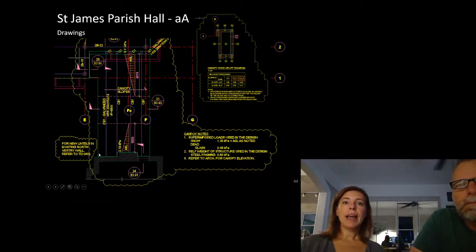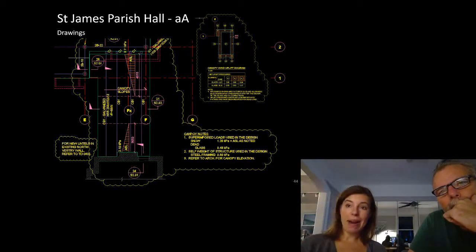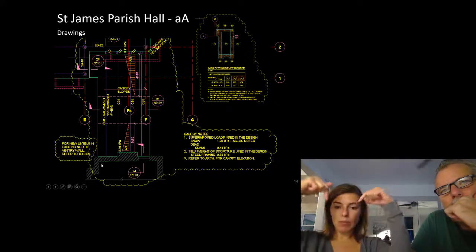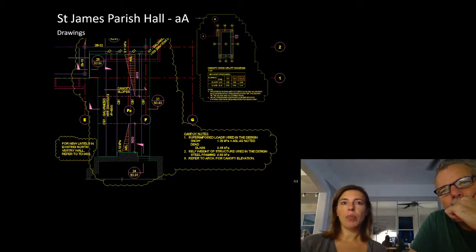So we're connecting something large into this existing building. We needed these connections to be doing the least amount of work they possibly could. Masonry is fantastic in bearing. So we wanted this right here to just be some point loads sitting on masonry where we could embed some steel plates and have that problem go away.